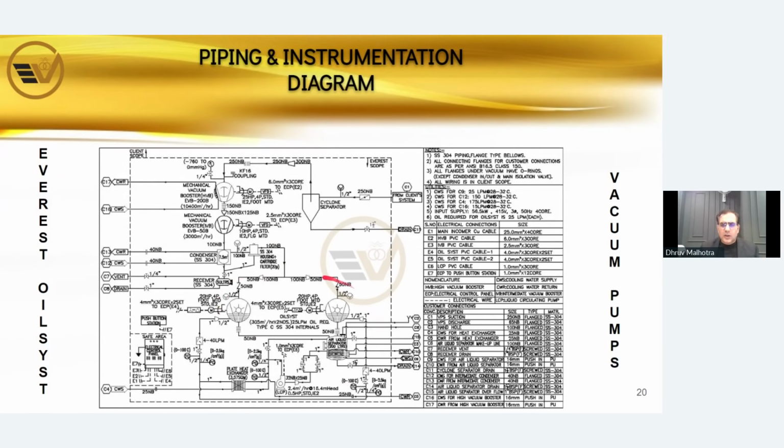These are both 100% recirculation pumps, which come along with their own closed loop circuit for recirculation, along with a plate heat exchanger and an air liquid separator. The discharge line of the air liquid separator, we recommend, should be sent back into the incinerator or the boiler that is available with you, so that any saturated oil vapors there, we can harness the energy out of those as well. The next is a typical ISO general assembly drawing.